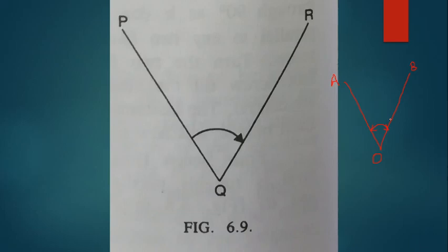Sorry, vernier A. And when you come to vernier B, what happens? Vernier B reading is actually 180 degrees more than the angle. So you can subtract 180 degrees from the 0 of vernier B, or otherwise simply keep the same main scale reading as we got in vernier A. That is more easy, I think.